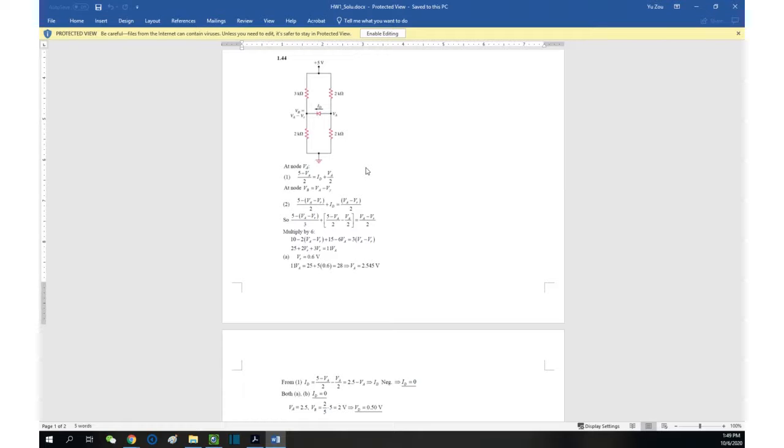Without this assumption, it doesn't make sense to start with the DC supply model. After this assumption, you apply this model, and then find ID, the current, to justify your assumption. These are two very important steps. Assume at the beginning, and then justify your assumption in the middle.